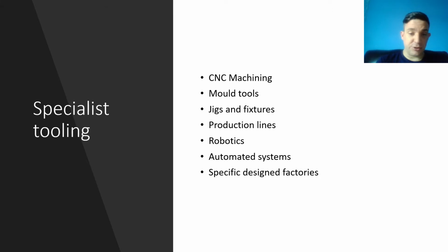Other things such as mold tools for an injection mold can cost many thousands of pounds to get the mold tool. Once you've got it, you can really quickly and really cheaply make lots of components. So a lot of your cost then is in the tooling rather than in the individual product being made.